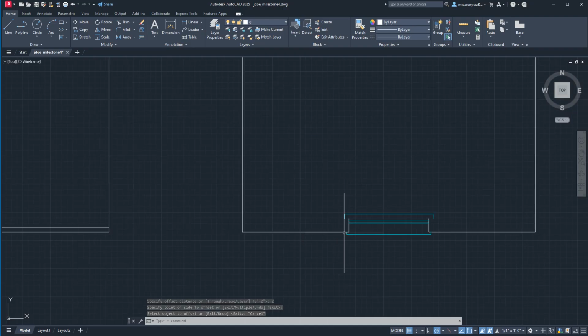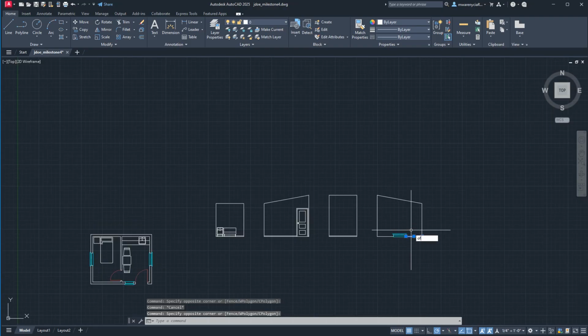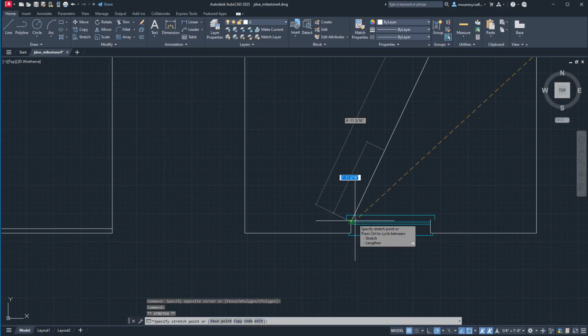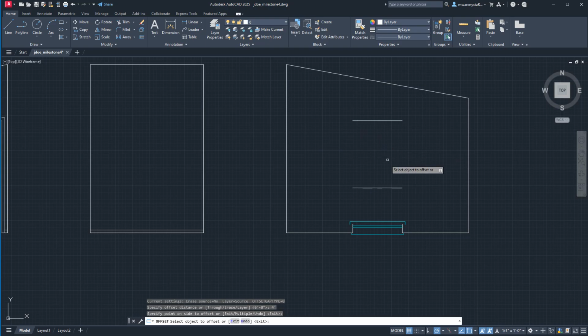This room, I don't think we ever determined what the height of these windows is going to be, so we'll call these 4 feet tall, so they're 3 foot wide. Windows, what we're going to do is we're going to offset this 6'8" up. And then we'll just reference this corner again. And then we're going to offset this back 4 feet down. So we're working under the assumption that all windows are framed at 6'8" at the top and then come down with their height. Once I've done that, I can go ahead and get rid of this.